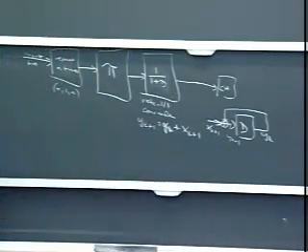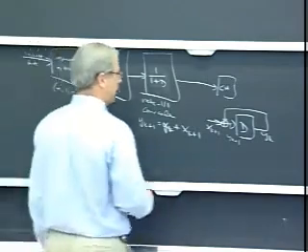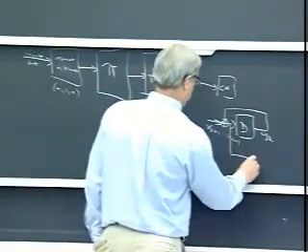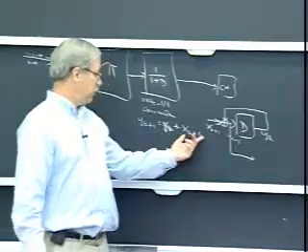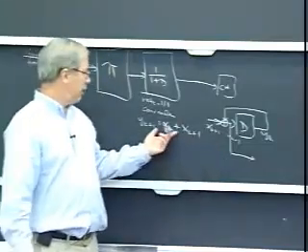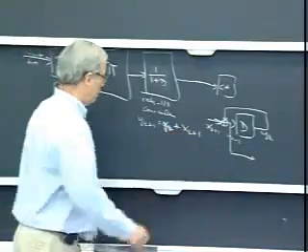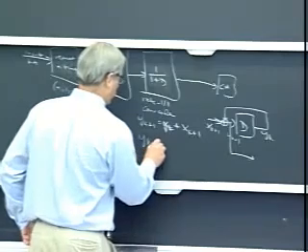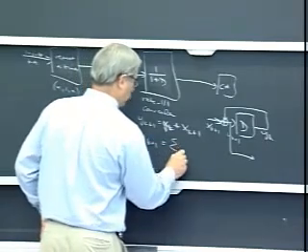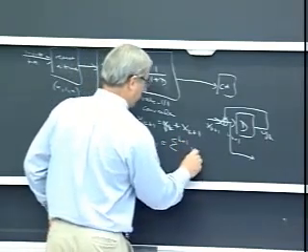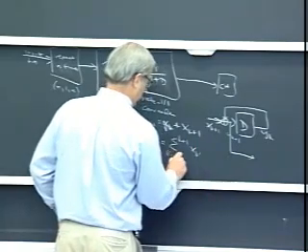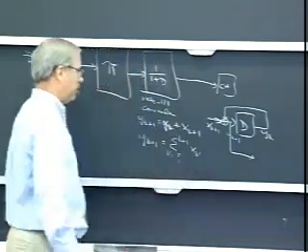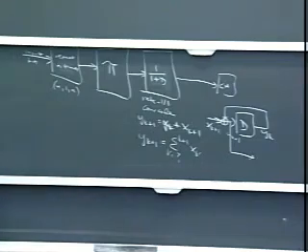Okay, so it's a very simple rate 1 convolutional encoder with feedback, where I guess we take this as the output. It's called an accumulator because if you look at it, what is y_k doing? You can show that y_{k+1} is simply the sum up to k+1 of all the x_{k'}, k' equals whatever it starts at, up through k+1.